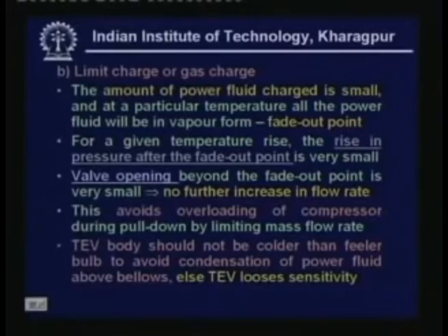Okay, whatever be the temperature, right? That means the flow rate reaches a particular value and it will not increase beyond that point. That means you are restraining the power input or power requirement of the compressor, thereby you can avoid the overload of the motor. Okay. However, there is one problem with this, that you have to take care that the thermostatic expansion valve